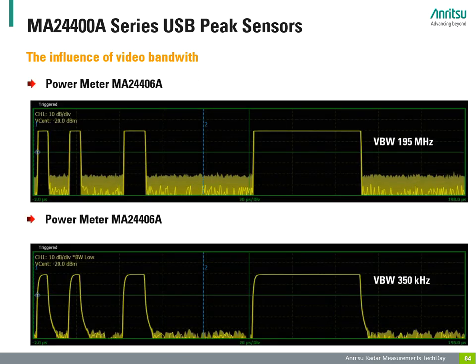Rise time and bandwidth are always inversely proportional, but their exact relationship is affected to some extent by nonlinear parameters such as slew rate, as well as by high-order filtering of the signal. For this reason, both parameters are often provided for peak power sensors.